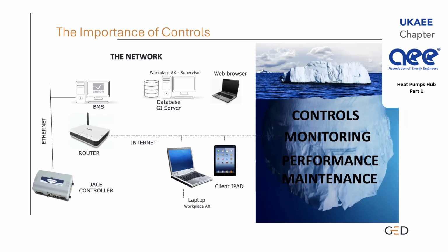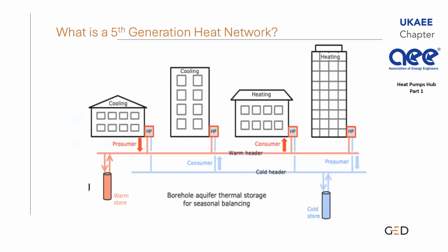So in heat pumps, there's a huge importance in controls. If I go back 20 years, when people were starting to put heat pumps in systems, you would find a heat pump company installer who would install the ground collector, free issue the heat pumps as boxes to the M&E contractor who would then install it. A lot of those systems really struggled to operate efficiently because no one had appreciation of the whole system and how it should all work together, not only the harvesting of heat at one end, but the actual performance of the heat pump and how you deliver that at the other end and how you do it with sympathy for a heat pump and efficiently. So controls are probably the overall thing that brings a whole heat pump system together.